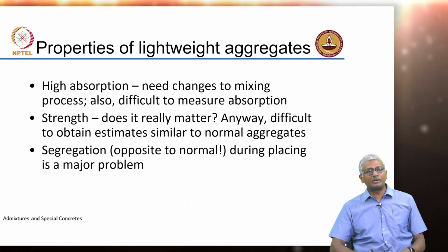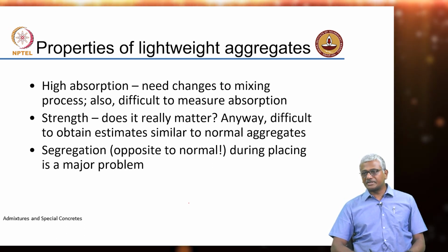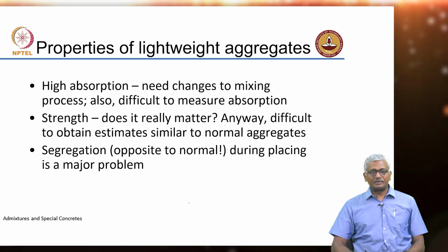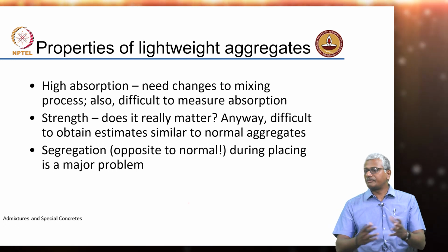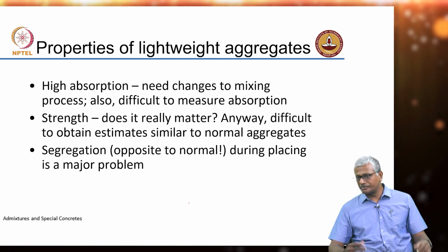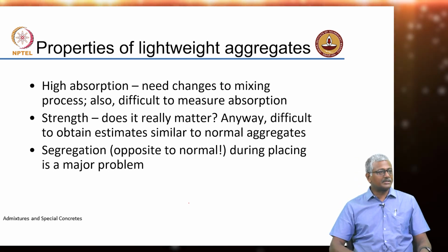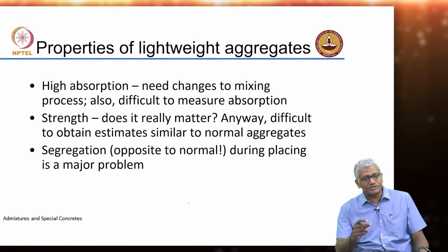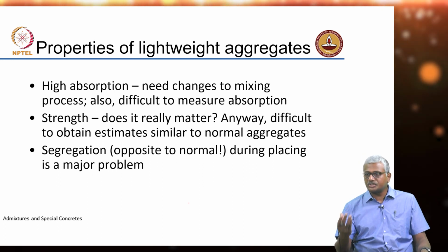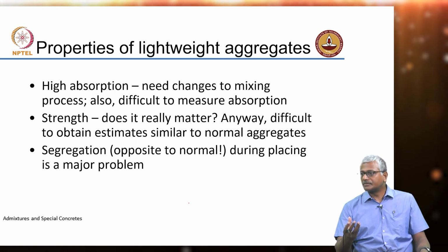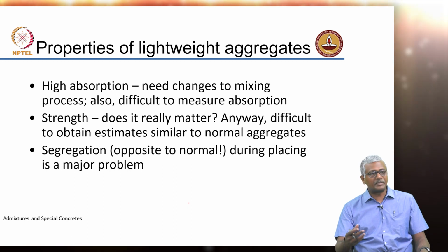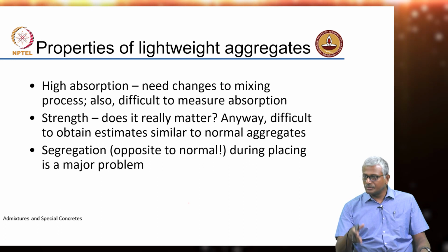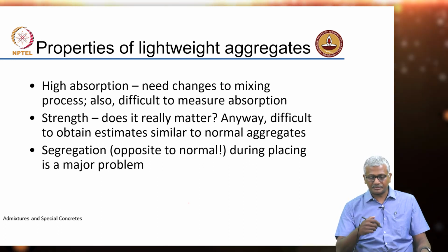When you do high strength concrete, your cracks are passing through the path of least resistance, and that happens to be the aggregate in the case of high strength concrete, and that causes the failure to be highly brittle, explosive, and that is something that you can also expect will happen when lightweight concrete is used or lightweight aggregate is used, because lightweight aggregate will in general be much weaker as compared to the paste phase, right. So, in such a case your concrete will fail through the aggregate, right.